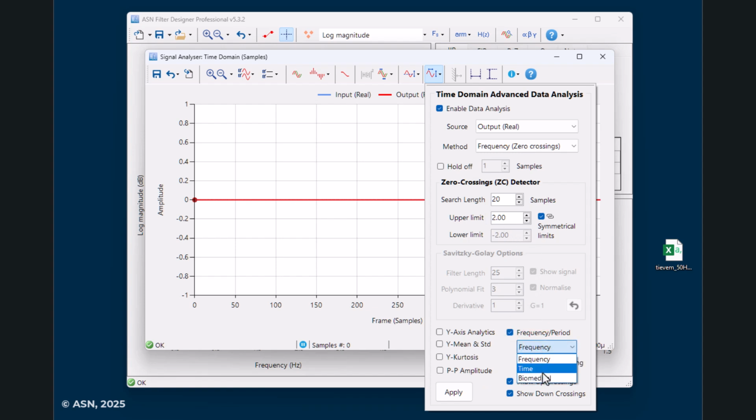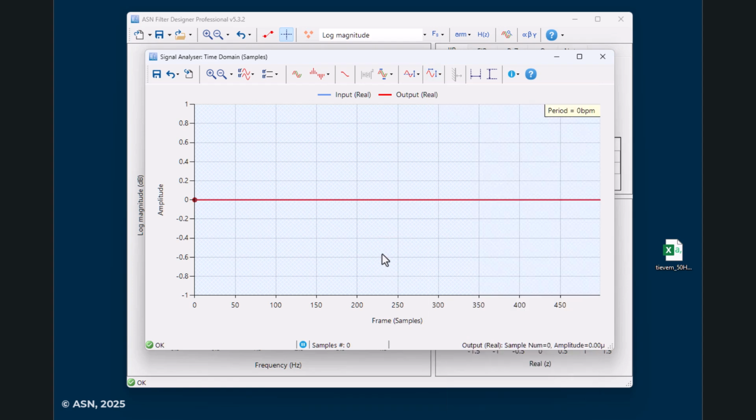Also, let's use median filtering instead of mean filtering to minimize the effects of outliers on the zero crossing estimates. And as we're just looking for the end of the sawtooth of our phase waveform, we just need to select down crossings.